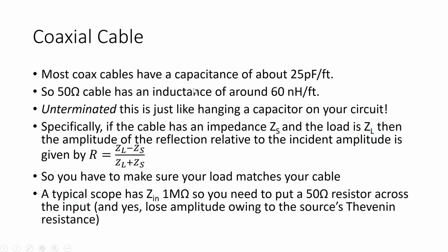Now, if you just take a piece of coaxial cable and hang it on your circuit, if it doesn't go anywhere, like for example a radiating dipole, it's just going to look like a capacitor, and so it's going to slow your circuit down.